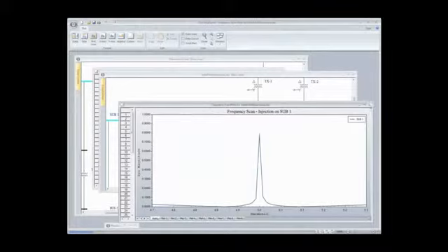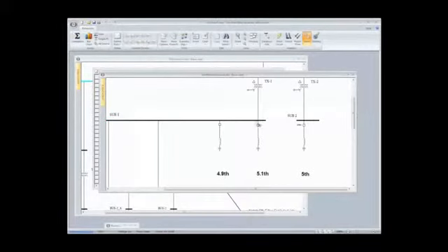Now, what's interesting, I'm making that happen. If you do a distortion with one filter on, you're at 2.7. Without it, it's around 9 or something for the harmonic load I have. So with one filter, I got down to 2.7. I put two filters on. Ooh, it goes up, right? Well, it actually didn't go up that severe. And so you might be thinking, oh, well, that's really not that big a deal, until you look at the current in each of the filters.